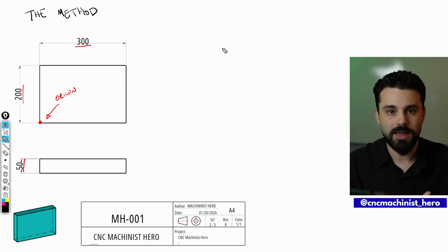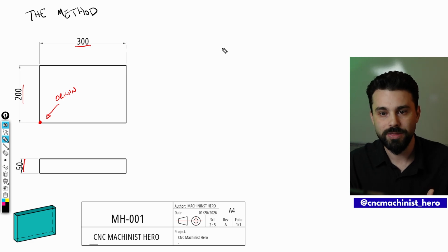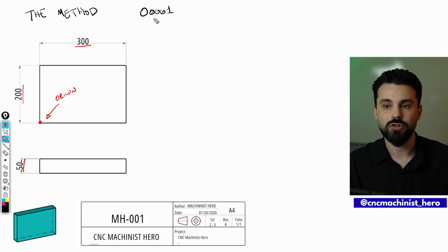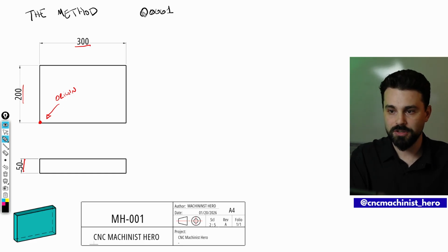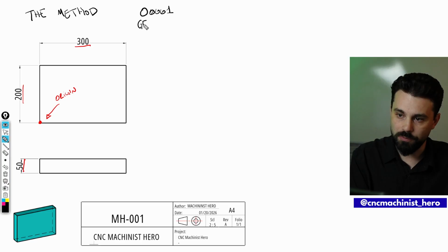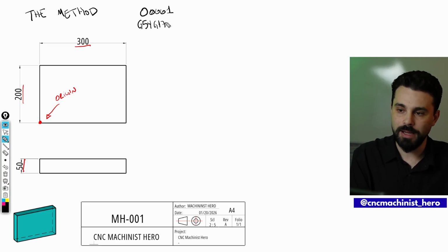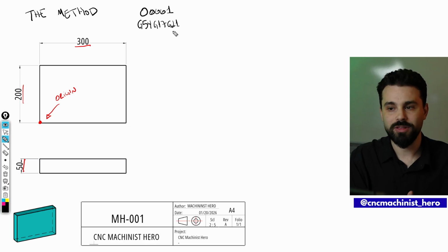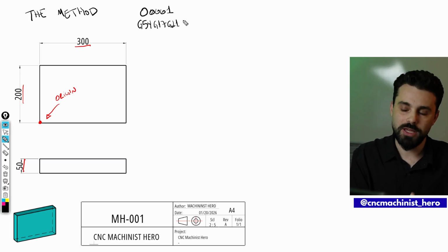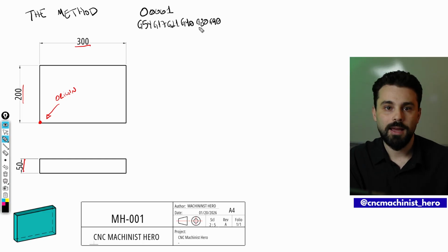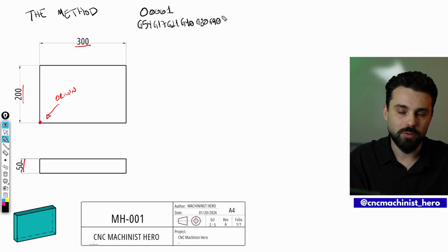Every CNC program that we create, we're gonna begin with a header. First program is gonna be program number 1. I'm using a FANUC controller here as reference. Every program is gonna start with a letter O and then 4 digits. Then our G code, that's our work offset, G54. G17 is XY plane. G21, I'm working with millimeters. If you want to work with inches, it's G20. G40 cancels tool diameter compensation. G80 cancels canned cycles. And G90 stands for absolute coordinate system.